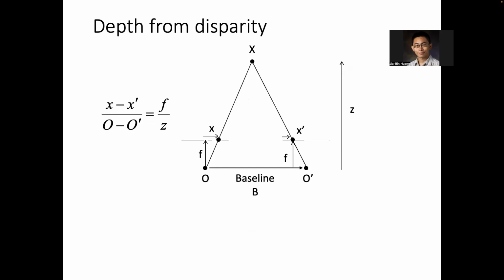But the top and this guy, these two lenses are mainly used for computing in stereo. You can see that they have a disparity. They are shifted horizontally, but their orientations are the same. It looks like this, right? You have one camera on the left, one camera on the right, and you have a focal length, and this is called the baseline.